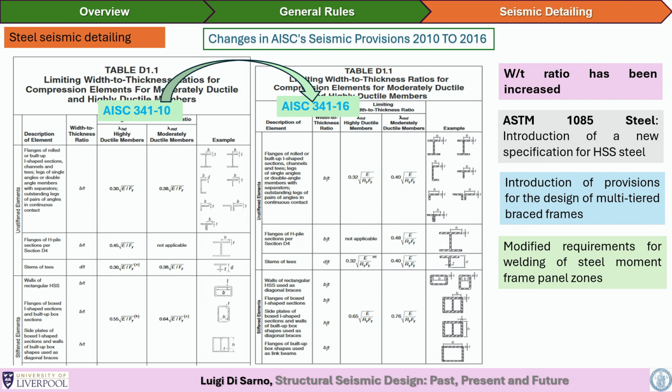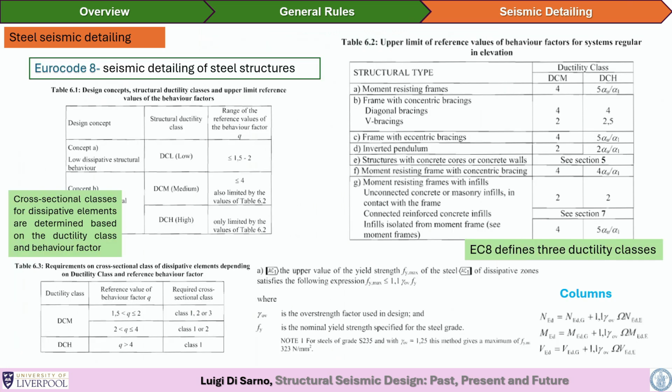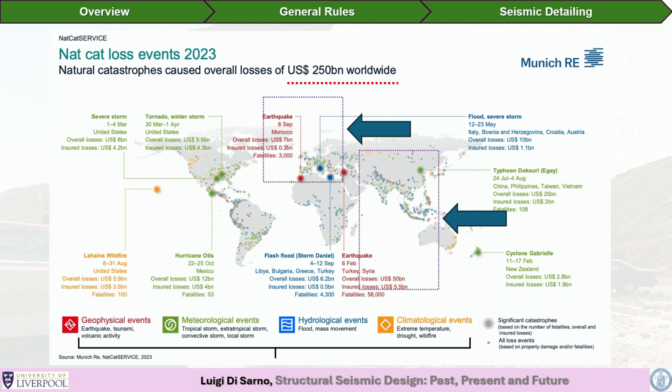And really going now to the last slides, I think. That's what happens in Europe, pretty much the same, with the controlling level of axial load, for example, in columns, because columns are very prone to buckle. So we want to limit the maximum axial load to 30%, for example, keep it low so they can dissipate more energy. And this drives me to the last part of the presentation.